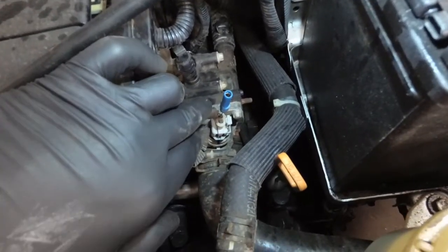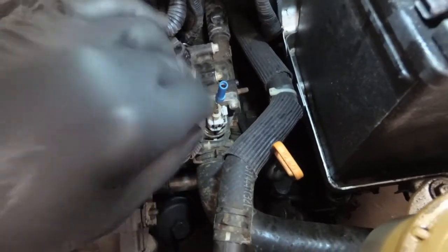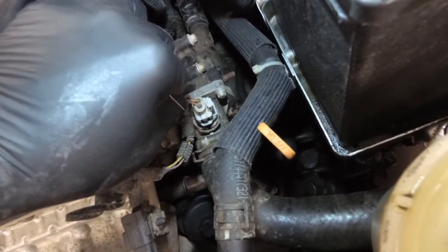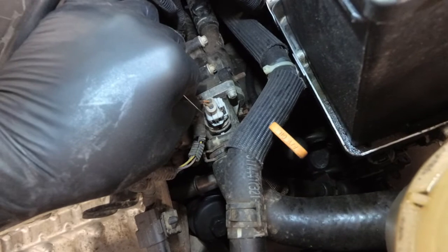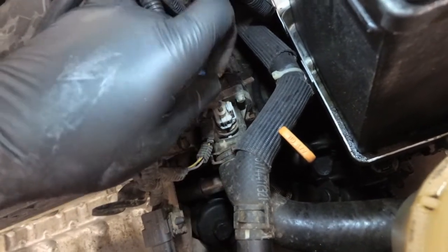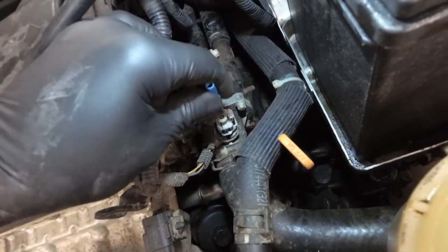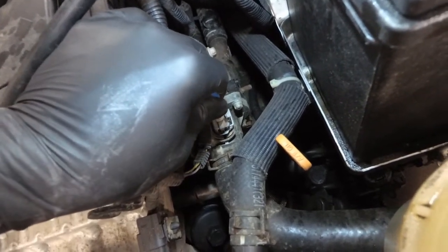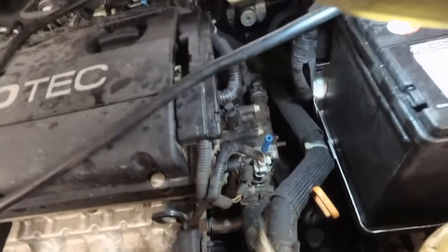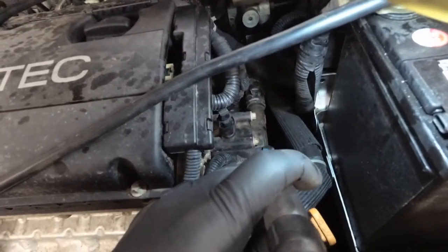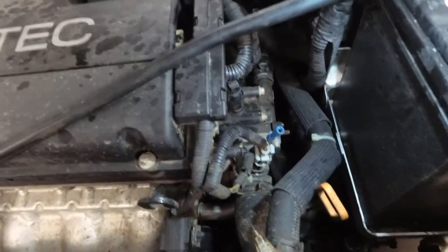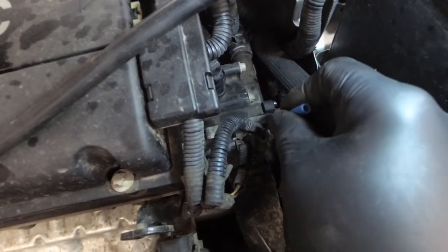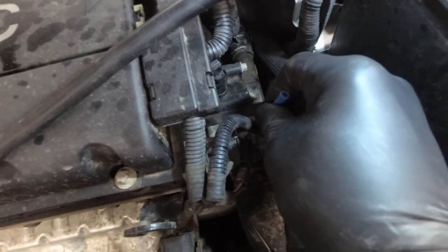There's the connector to the thermostat, and if I pull this pin out here, you'll see there's an orange-black wire and a brown, looks like a brown wire, might have a trace on it. So I'm back pinning this orange-black wire, sliding it up to the pin, and with a test light to ground. Oh, I guess I missed it. Try this again. There we go.